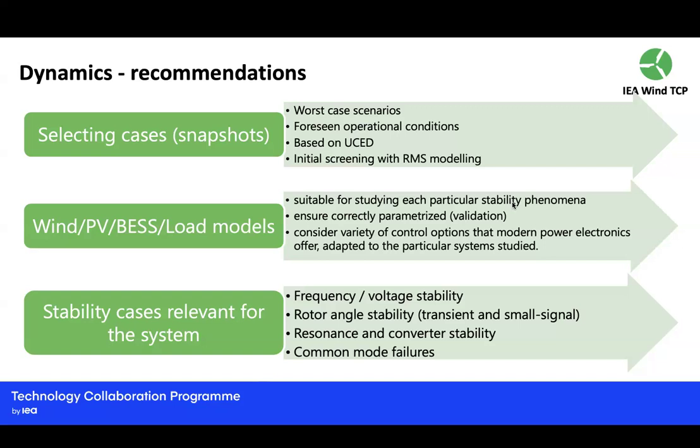This was overlooked over time because system operators have less visibility of load types and load characteristics, and less capability to model them, but now the system becomes more sensitive to how this is modeled. From that you choose cases that you would like to study for stability impacts, which lists the different types of stability you need to study, and based on which type of stability you are focusing on, different details matter, and you may also use different tools to solve it.